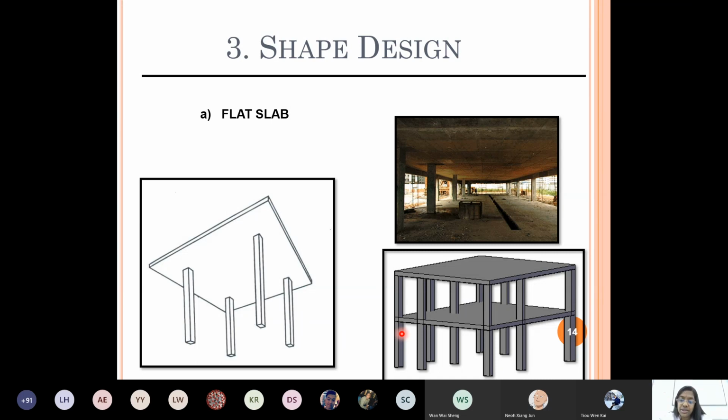Chances of moving out, right? Chances of coming out of the position. Care should be taken, maybe bay wise, like 3 meter by 3 meter, they will check all the covers, then start pouring the concrete. And sometimes the vibrator they use to level the concrete can also disturb the cover. So care should be taken always to check whether the covers are in position so that you will have complete finish. Otherwise your steel will be protruding out or there will be no concrete at the steel area.